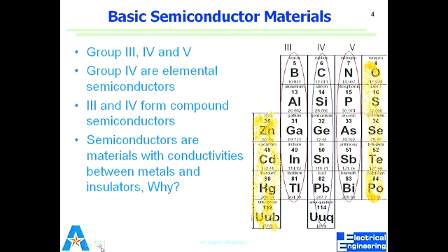Okay, yes, you're right. But more specifically, a diode is two types of material, which may be the same element, but the type is, when we say N type or P type, they are in intimate contact with each other, right? So they are bound to each other. Or maybe that was one bulk, but we doped one part to be P type, the other one to be N type, right?